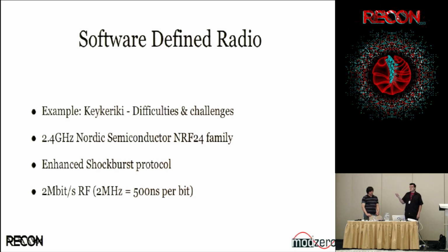So the receiver will just drop any packet that doesn't match the preamble and the configured MAC address. So from my point of view, I would like to sniff all the traffic without utilizing software for it. So I'm lazy. I'm also using the Nordic semiconductor chips, but I need to know the MAC address to set up my own radio receiver properly.